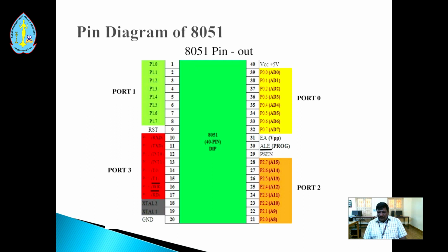Next we have 2 oscillator pins, called XTAL1 and XTAL2, which are for the crystal oscillator. The next pin is ALE, which is address latch enable. The next one is reset. That is all the 40 pins of the 8051.